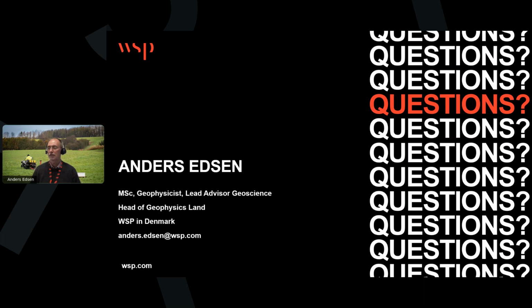Then there's a question how geophysics can help for existing facilities. And with existing facilities, I guess it's meant existing boreholes or existing water utilities. One of the main drawbacks of EM methods is that they cannot be used in culturally developed areas. That means that they will couple to cables and power lines, metal fences and whatnot made of metal.